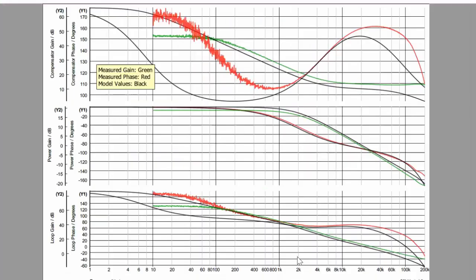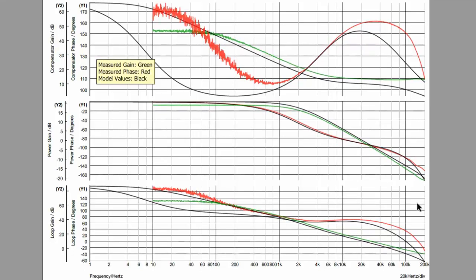So what I've got here is the black curves were the simulations. The colored curves were signals that I actually imported. And so down here is the full loop response, and it looks pretty close, but you can see at this black curve up here is a pretty big gap from where it's supposed to be down here. And when you split that up, you can see, okay, this is the power block right here. Everything looks pretty clean in the power block. The simulations are right on top of each other, and it's when you go up to the compensator that things started to deviate a little bit.